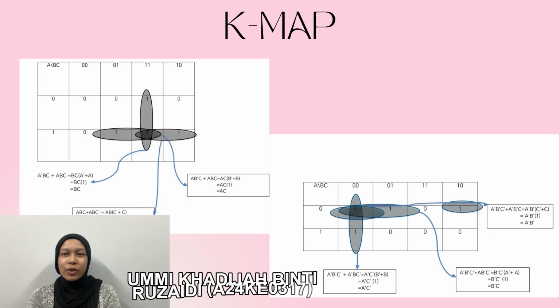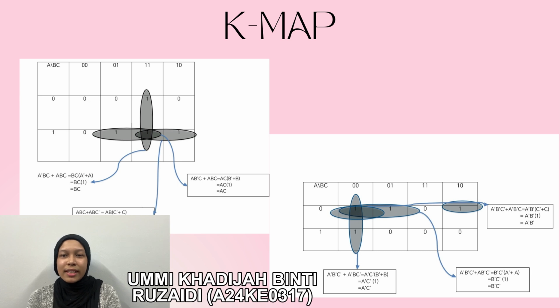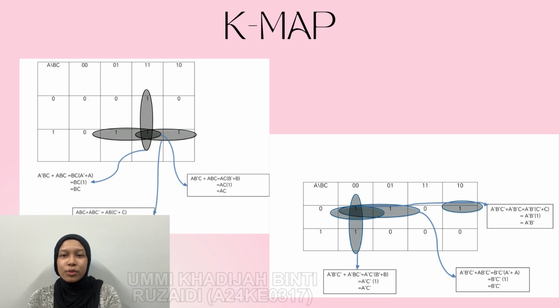To express the equation from the truth table, we decided to use K-maps to obtain the output expression. For output X, that majority is approved, we get F equal to AB plus BC plus AC. For output Y, that majority is against, we get F equal to A bar B bar plus B bar C bar plus A bar C bar.